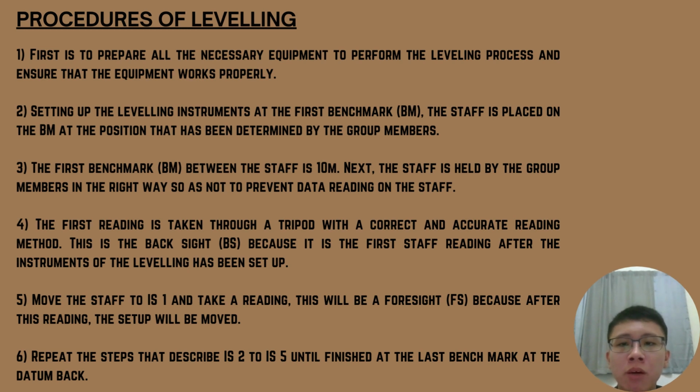First is to prepare all the necessary equipment to perform the leveling process and ensure that the equipment works properly. Setting up the leveling instruments at the first benchmark BM, the staff is placed on the BM at the position that has been determined by the group members. The first benchmark between the staff is 10 meters.